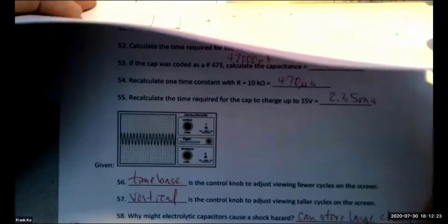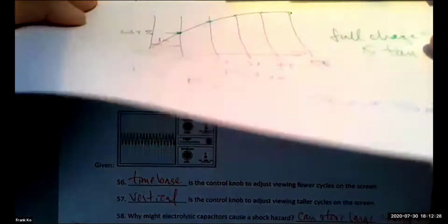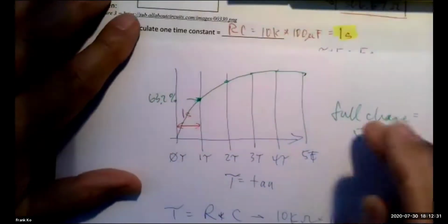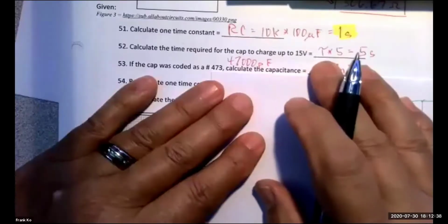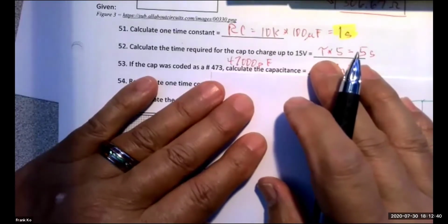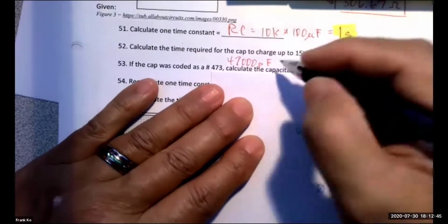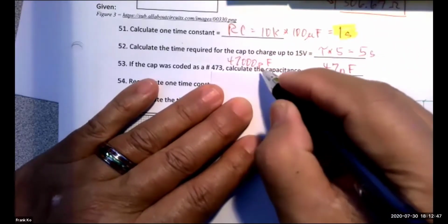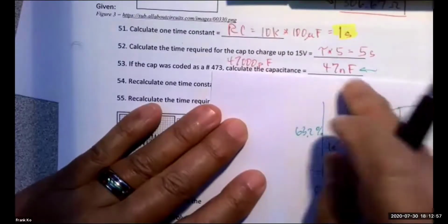Next question is number 53, having to do with the capacitor. What is the value of capacitance for number 53? Javier. 47,000 picofarads. 47,000 picofarads. Punch that into your calculator. That's not proper engineering notation. Yeah, this is your intermediate value. I write down 47,000 picofarads, but that's not what I would put on the answer sheet. 47 nanofarads. There you go. Good job. It's 47 nanofarads, my friends.